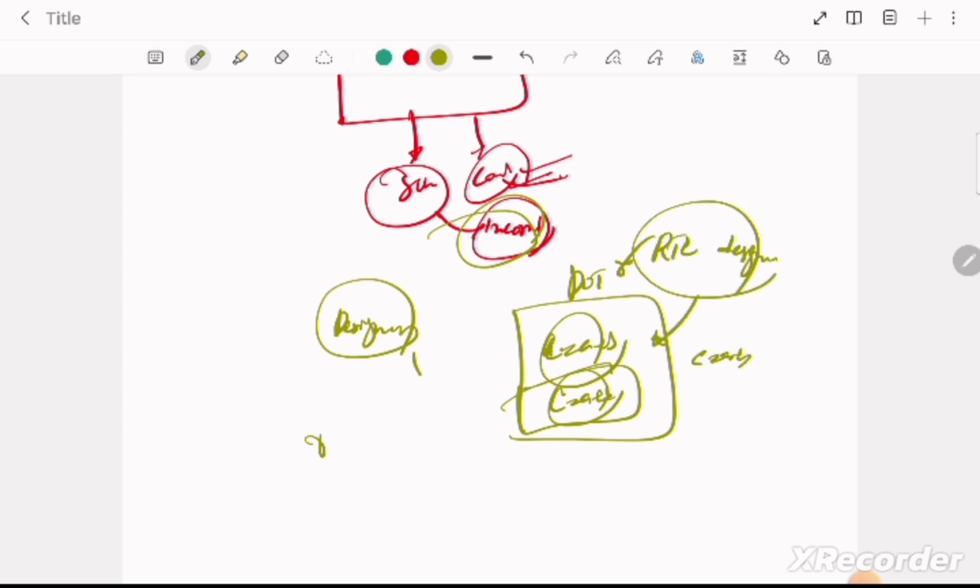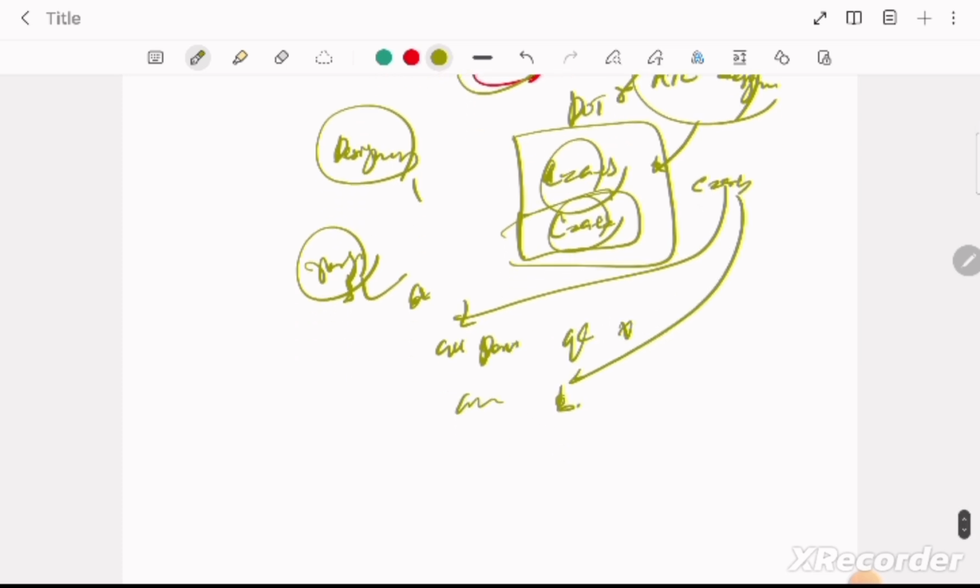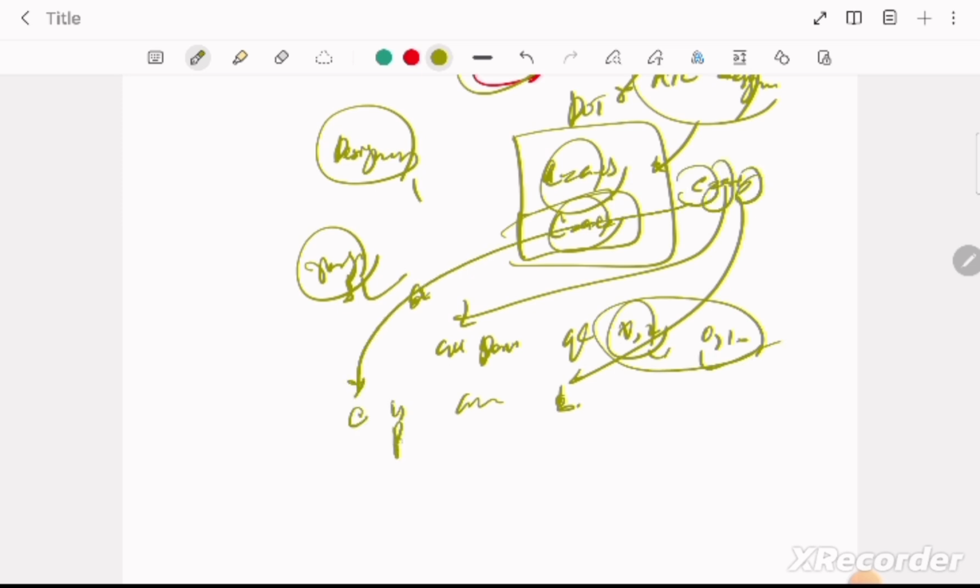And here is the verification person. He has to verify. He has to write all the test cases, or test harness we can say. He has to put all possibilities of A, all possibilities of B, including X and Z. He has to put everything, 0, 1, X, and its combinations for both of these. And then we see how C differs with respect to the correct output. If it is coming the same, we will say that this design is correct. Now it can go for the further steps.